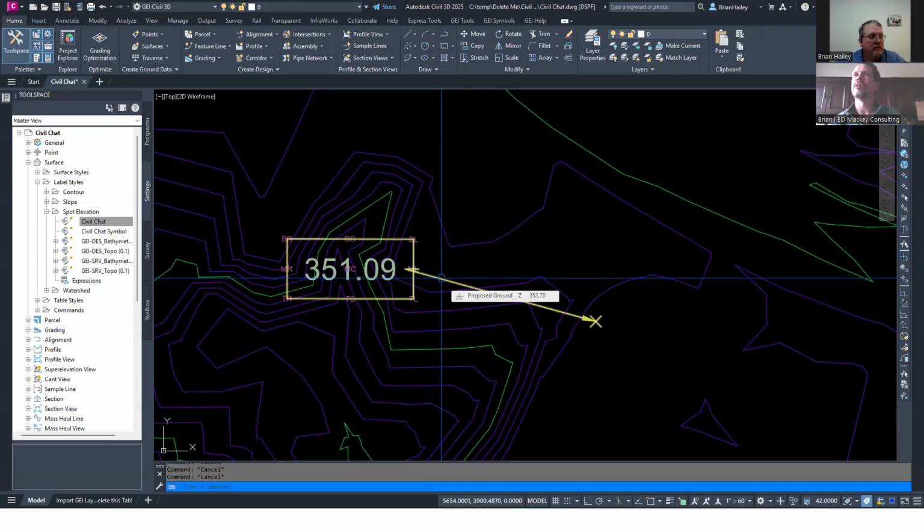So our first question is, how can I make a pipe object style to represent a concrete jacket around a pipe? Say a 6-inch sewer line with a 6-inch thick concrete jacket. I opened a Civil 3D file with a style for a pipe object that shows AR-CONC hatching for the jacket around the pipe. The jacket moves automatically with the pipe whenever invert or horizontal geometry is modified. I've tried reading the definition of the style from the style editor, but it doesn't show anything different from the styles without a jacket.